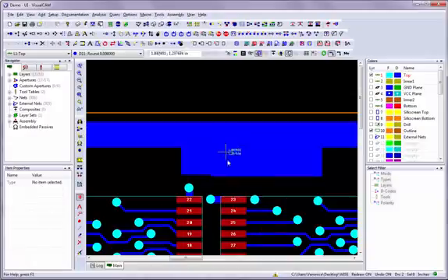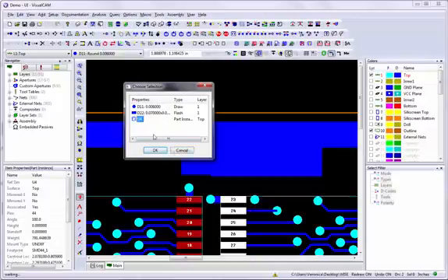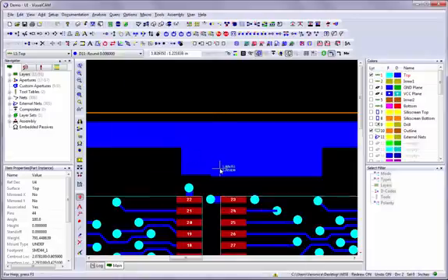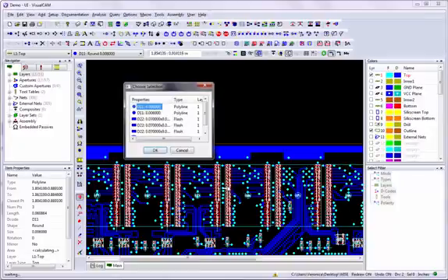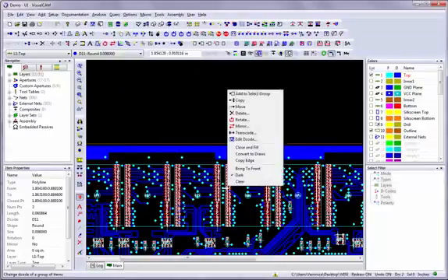If more than one object is located near the mouse pointer when you right-click, such as a flash and a polyline directly under your pointer, then you will first be presented with a Choose Selection dialog, prompting you to select the specific item to be edited or queried. If you are zoomed out, you will notice more objects are presented from which to choose. To narrow the list, zoom in on the item you want to select. Once you choose the correct item, the right-click menu will appear offering you several commands from which to choose.